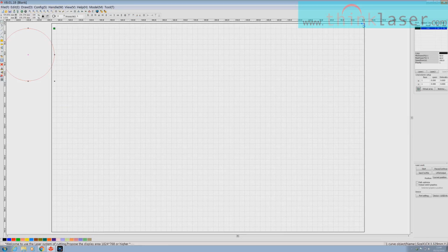Driving the head to the top right hand corner is far less intuitive as far as positioning your work than it is if it's on the top left hand corner, which is where everybody conventionally works from, reads from, writes from. To try and overcome this problem, what I would generally say is try and get your mind around the idea that your first object will be set there and you work right to left and down the page rather than left to right across the page. Now, although it seems like a lot more, in reality that's only 4 datum points, 0, 0 positions and origins that you've got to think about.